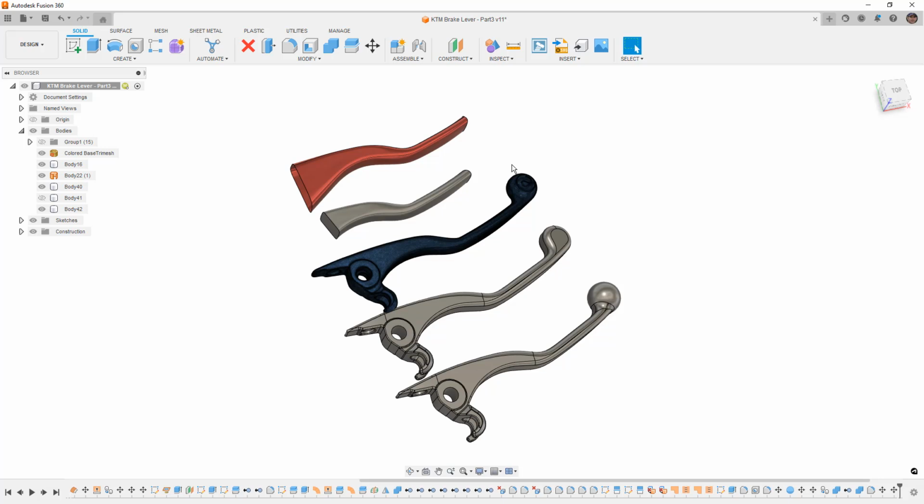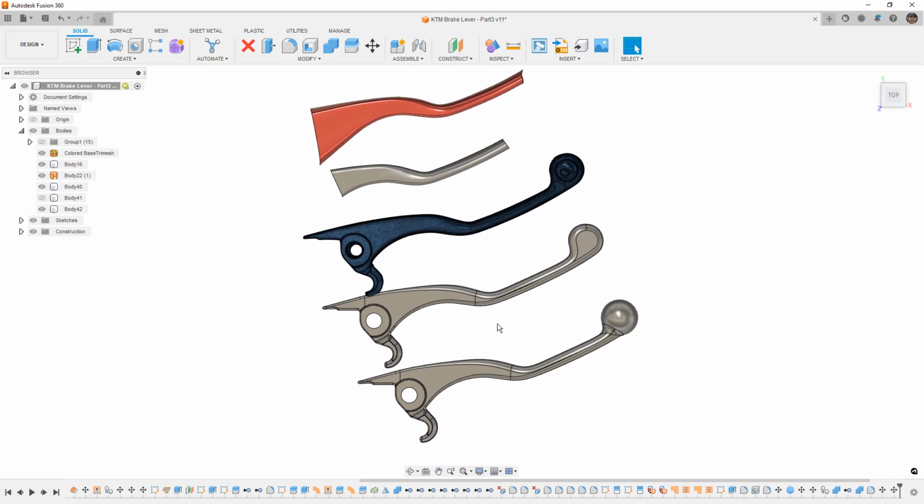And then we can pull down to the mesh at certain points, and we can get extremely close to the shape without all the downsides that we get from using the mesh section sketch. Now, the problem with that on a part like this lever is we actually end up with a problem going to more prismatic features. So like the pivot point, the hook, the flat face on the top and bottom, transitioning from a complex surface, even one that's high quality, into those features ends up getting a little bit messy at the seam between those.